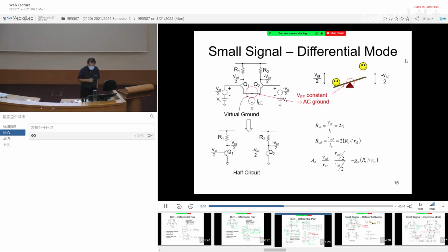So in IC design, usually 1% is considered quite easily doable. You don't have to pay too much attention, quite easily attainable. Now, in differential circuit, if you try to analyze the gain, one thing that we would apply is the so-called half circuit concept.